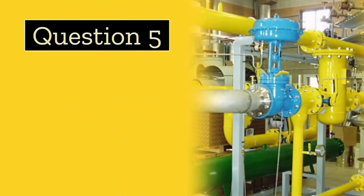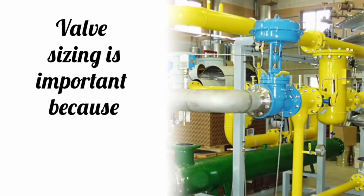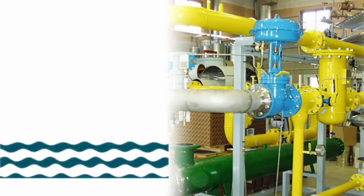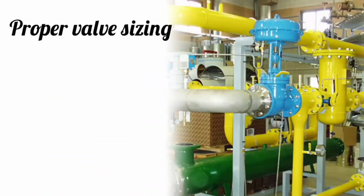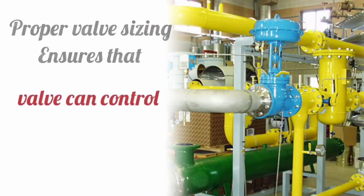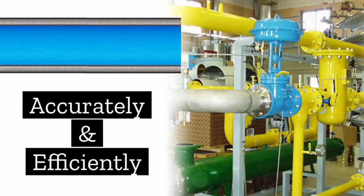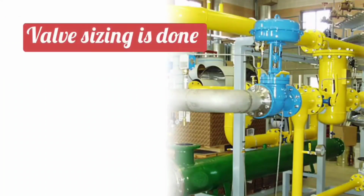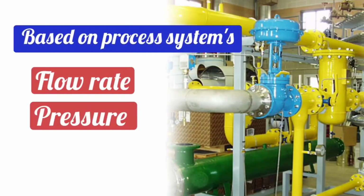Let's take the next question. What is the importance of valve sizing? How is it done? Valve sizing is important because it ensures that the valve is properly matched to the flow rate and pressure requirements of the process system. Proper valve sizing ensures that the control valve can control the fluid flow accurately and efficiently. Valve sizing is done by calculating the required flow coefficient, which is based on the process system's flow rate, pressure, and other factors.